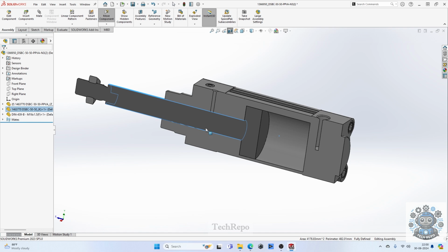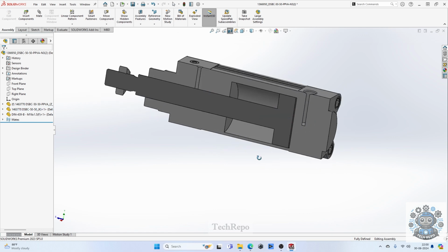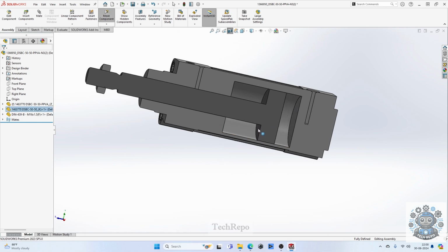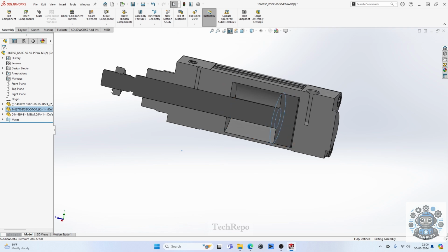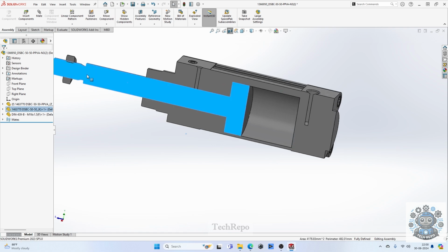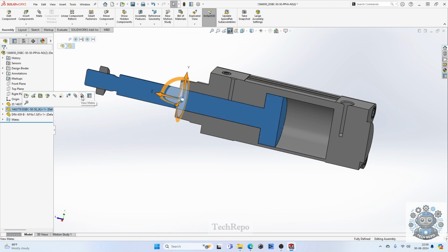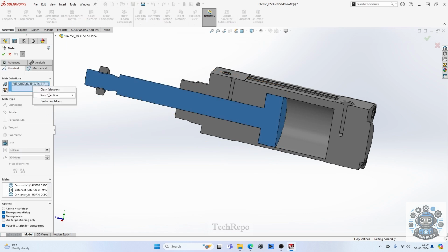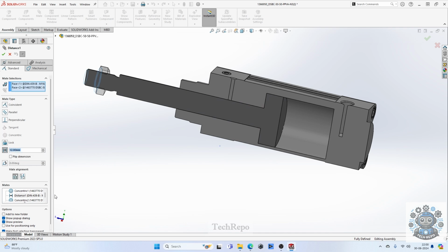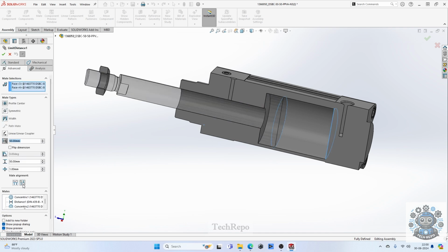So this is how we define a mate for a cylinder. The same thing you can do for any mechanism. It is bound to move between a specific mm. You can also define the width mate if you are very sure that the thickness of the piston shown here is perfect. Since we downloaded it from Festo, the width is perfect, so you can also define a width mate stating that it is free to move between the 2 ends. In case you didn't see the video that we have posted earlier on the advanced width mate, you can go ahead and have a look into it.